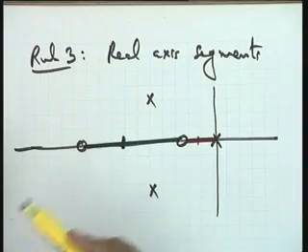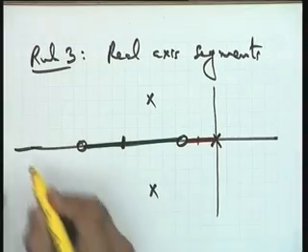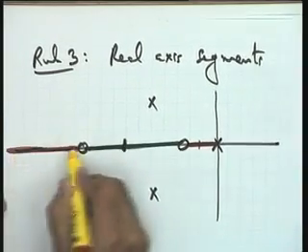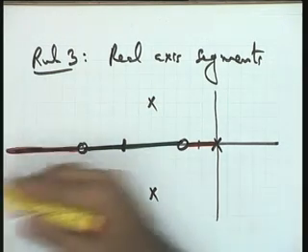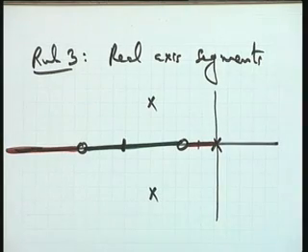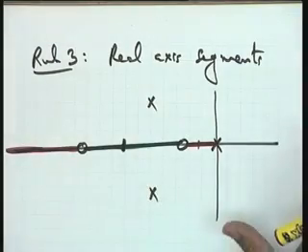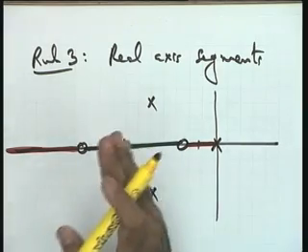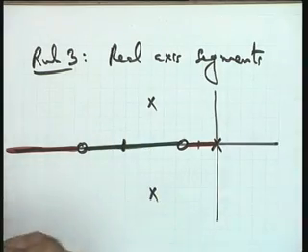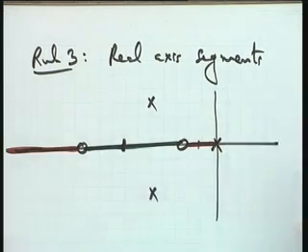Look at this particular segment again. It is again odd, and therefore this lies on the root locus. And how about this? Naturally 0 is even, so this also does not lie on the root locus as far as the right hand side is concerned. So out of the entire S plane, the real axis has been appropriately scanned. You simply look at the count of the number of open loop poles and zeros to the right of that particular point, and you can make a decision about the total segment by application of this rule.